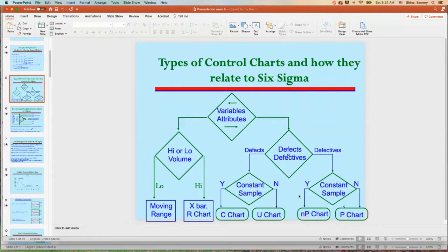How do we do that? We do it by the number of defective units, the number of rejected units. When I say defective, it's the same as saying rejected. That means when we make a measurement, you might put it in a machine, and the machine gives you a green or a red light. So we count in a sample, and the sample usually is much bigger than the sample for the variable.